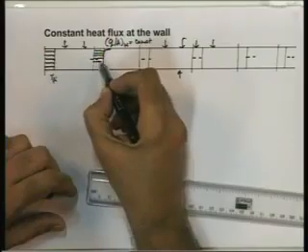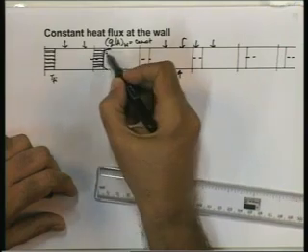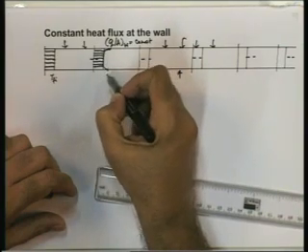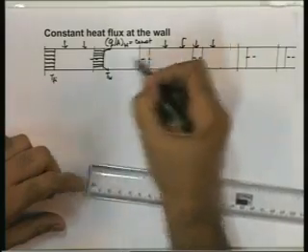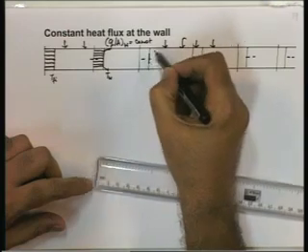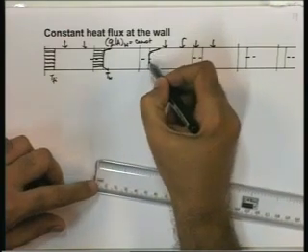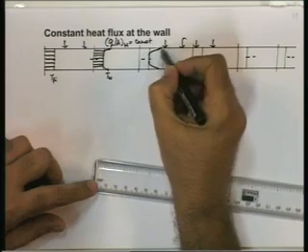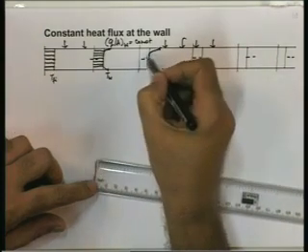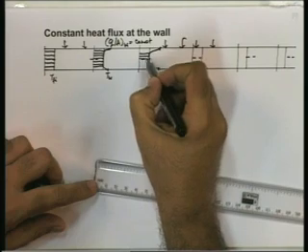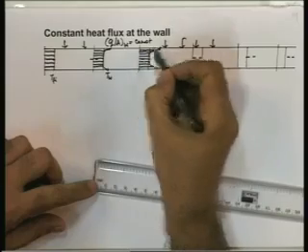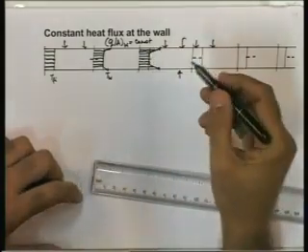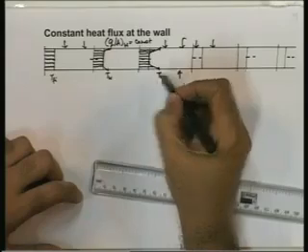So after some distance we will have a flat profile in the center and rising to the wall. This would now be the wall temperature at this location. As we progress, more and more laminae will get heated and we will have a temperature profile like this. The gradient at the wall will remain the same. The center portion, which would be unaffected more or less, would remain flat, but that would narrow down. T wall would naturally be higher now.